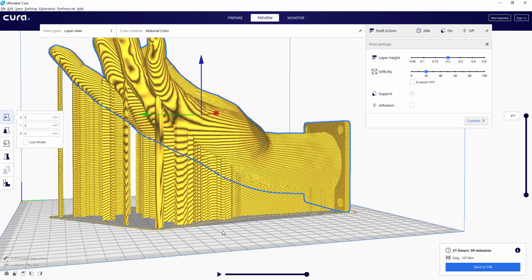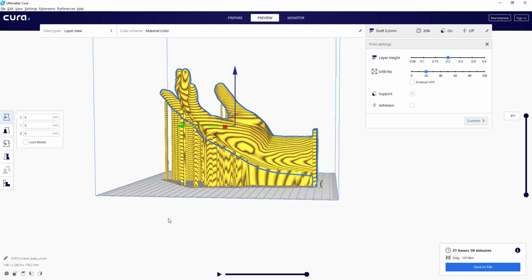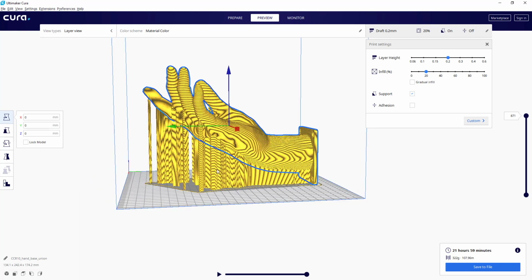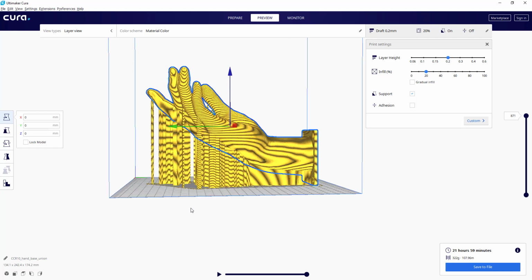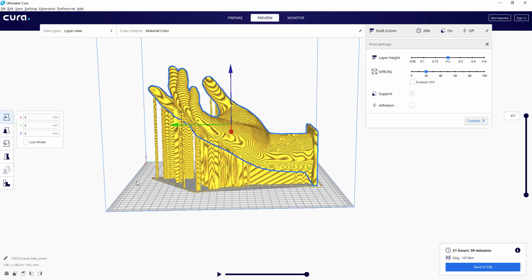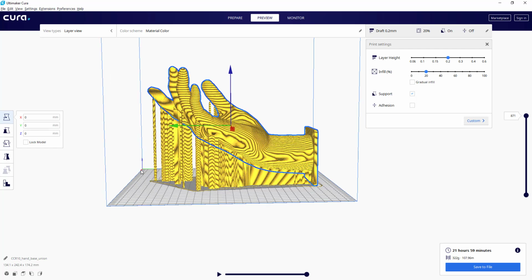How does most softwares of support structures work? It is quite simple. Fused deposition printers, due to its way of printing layer by layer and due to its Z axis, cannot print those parts in a 45 degrees angle. A 45 degrees angle from that position cannot print correctly the layers, and they are called suspended layers. This is the reason why it needs help of a support structure. We'll see now the color scheme.